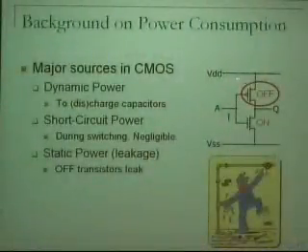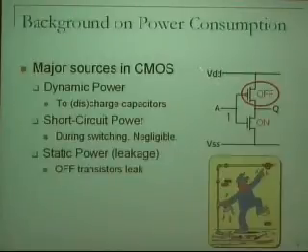The basic mechanism to get rid of this leakage is to turn off the circuit, meaning that you just do not let the supply voltage be here. But you can only do this when the system is not working, is not doing anything useful. And especially for some things like cache memory, you cannot do that because you have some important values there.